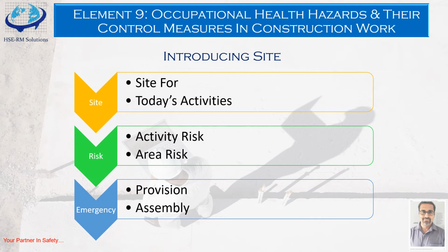So you will also be telling them that the risk persists because these activities are going on, and you need to tell them where people are: where is the supervisor cabin, where is the construction cabin, where is the electrical cabin, all the contractual cabins, where first aid is available, where is the security gate, where is the assembly.